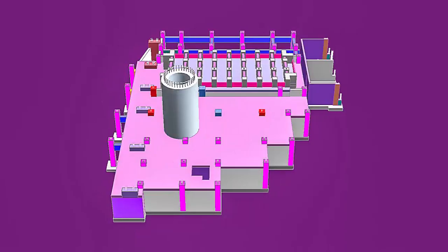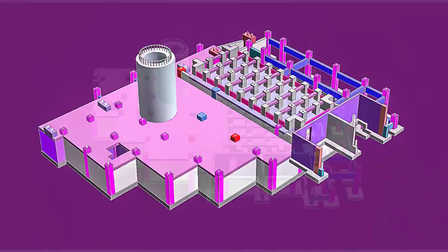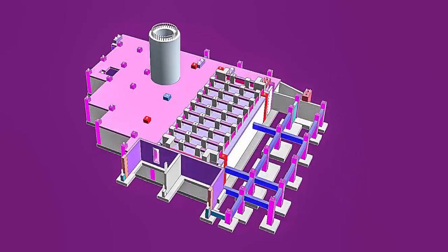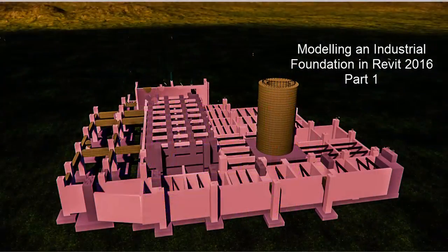When CAD arrived in the 1980s, this same drafting process was implemented on a computer. CAD programs such as AutoCAD and MicroStation are simply pencil and paper drafting on a computer. That's all they are. An AutoCAD drawing is simply a collection of lines and geometric shapes. What these lines and geometric shapes represent is unknown to AutoCAD. Drafting always involves duplication of information. One of the piers on this foundation is shown 19 times on a total of 17 drawings. If the basic geometry of this pier were changed, each copy would have to be modified one by one.